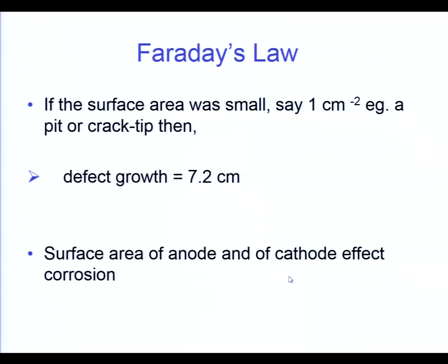And this is an important point because it's exactly what we see in things like stress corrosion cracking. The surface area of the anode in a stress corrosion crack is tiny.